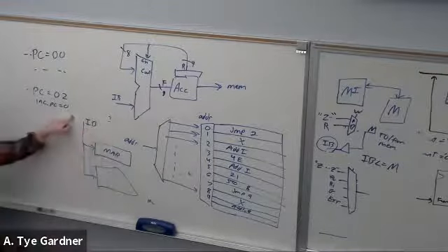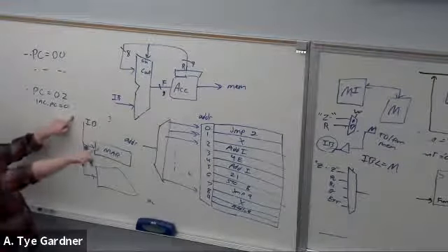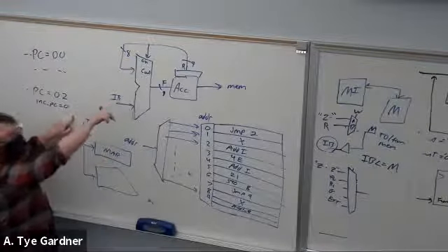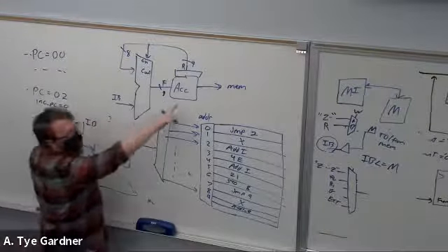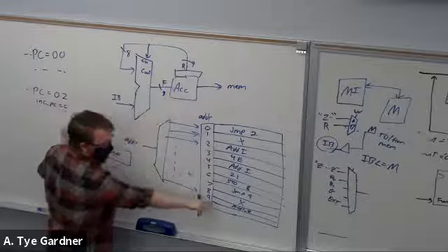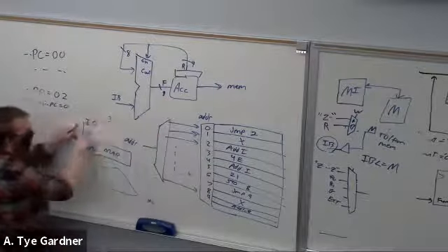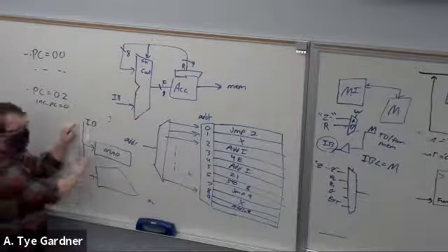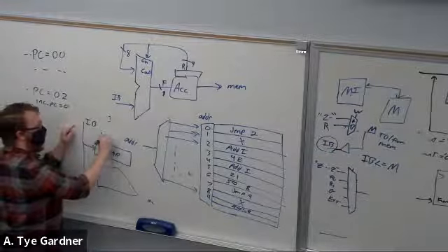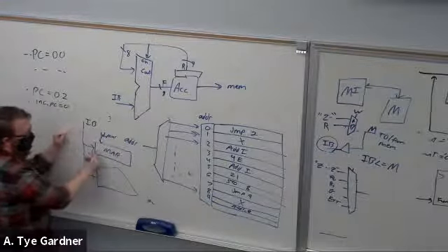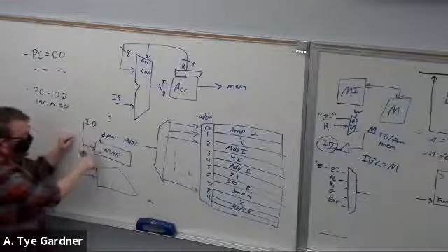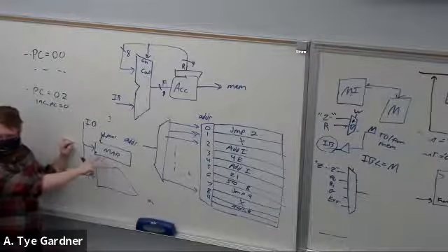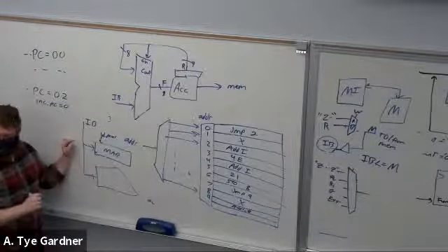This is the internal bus, right? And now that's tied to that output, which is tied to R. So the value, that address 8, got stored in this accumulator, now appears on the internal bus. I assert load MAR, and the clock cycle happens, and I store that value into the MAR. And now I can use it again. That makes sense. Okay, good.